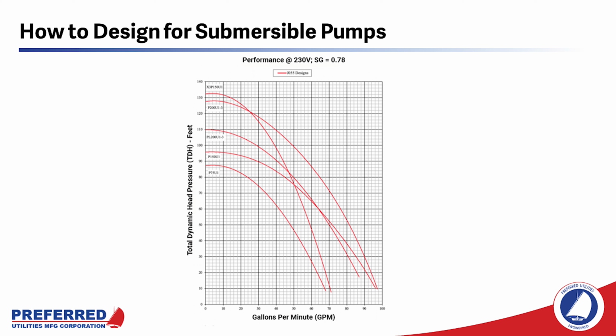We brought out a technician from the manufacturer of the pumps, and he looked it all over. We showed him the pump curve that said that we should be able to get the fuel up to that height, and he shrugged his shoulders. So you can't trust the pump curves. You've got to take them with a little bit of grain of salt and not push them to their limit, because they can be a little optimistic. That being said, there are a couple of situations where you have to use submersible pumps.